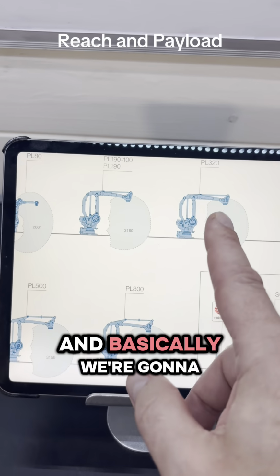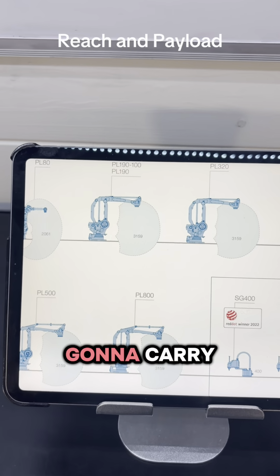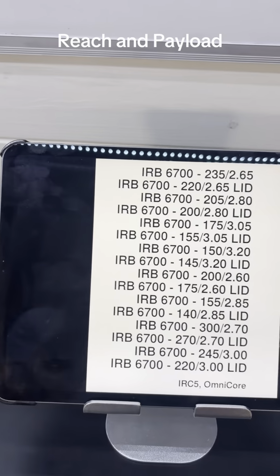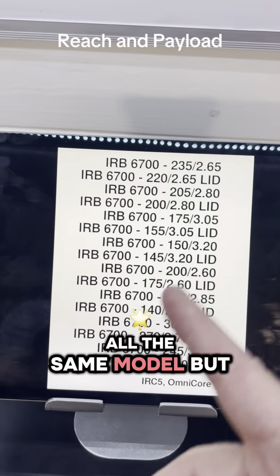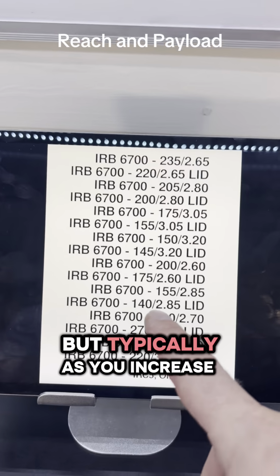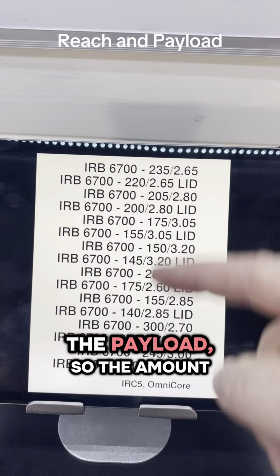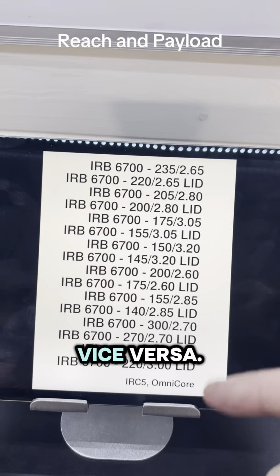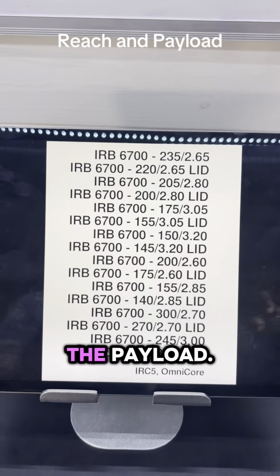And basically we're going to have to work out what payload you're going to carry and how far you need to move it. And so this is a load of ABB robots, all the same model, but different variants, and some will have more powerful motors and stuff, but typically as you increase the payload, so the amount you're carrying, then the reach decreases and vice versa.